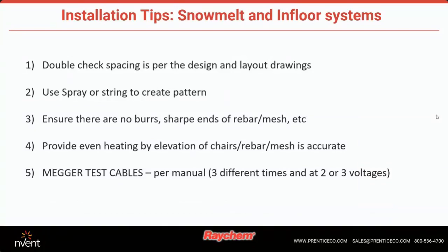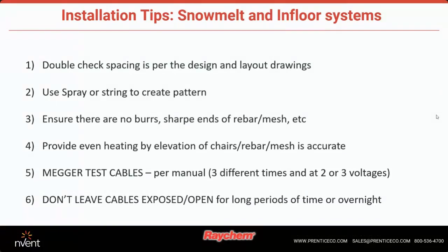Again, same thing applies. Megger testing, installation testing is very, very critical. Make sure you look at the manual, make sure you do that on all 3 different occasions and at the voltages that apply to the product. And then lastly, I'd say this again, because this is probably the number one thing that I find becomes a problem: when water gets into the cable. If it has not been secured, even securing it with electrical tape at the ends is better than leaving it open to atmosphere and allowing water to get in.